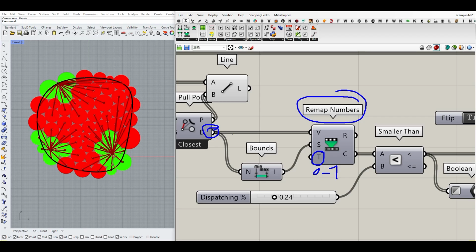Okay, so what you have to do is to say, okay, I want to scale the numbers. What is the domain? You just use this simple bounds component. You give it to it. It's going to be, okay, it's between, I don't know, between 5 and 80. So you give the values, define the bounds of the numbers, and now you just give the target domain. By default, it's 0 to 1, which is perfect because we need them to be scaled into 0 to 1.